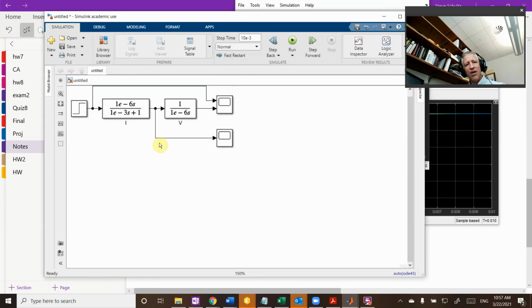So this is how I solved my differential equation by having my transfer functions in the S domain, or the Laplace domain. My input is in the time domain and my scope is going to convert it back into the time domain. So my inputs and my outputs are in the time domain. My functions, my differential equations are all done in the Laplace domain, and then I can get everything to work and I can model these dynamic equations and do different things.